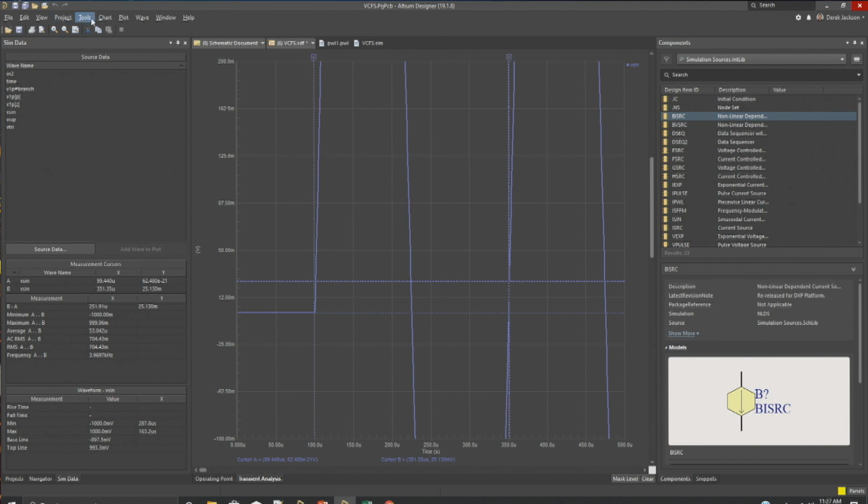Now under here you can run a fast Fourier transform on your display of waveforms. If you go under the chart with the FFT, but typically with the FFT you want to run your simulations with as many full periods as you can. The more periods typically gives you a better result with your FFT, and of course that'll show you the main Fourier frequency point. If you have any harmonics coming off of that, it'll reference those. And so that's based on the display data.